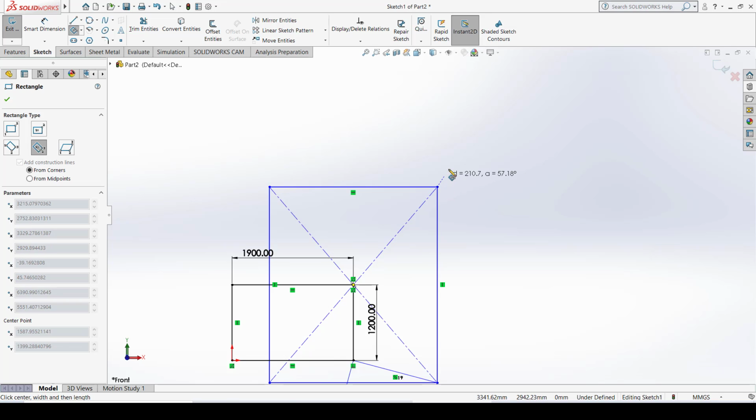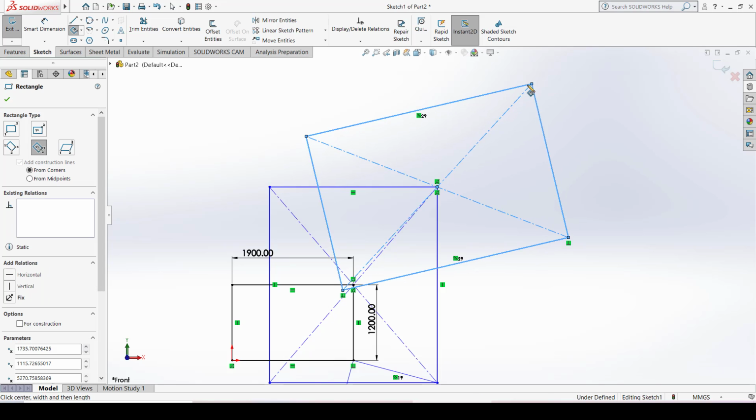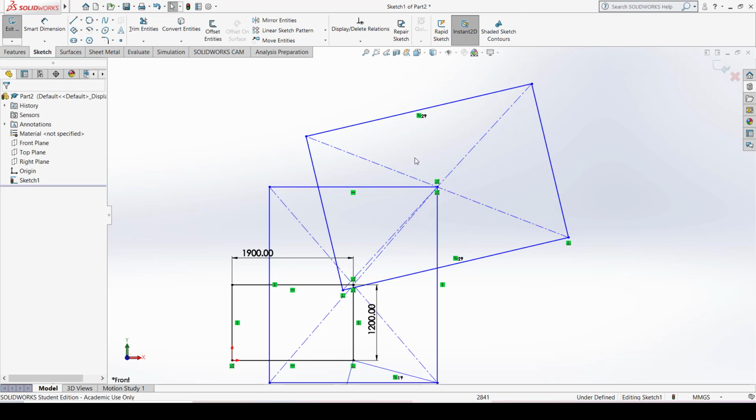Okay, so let us say first is the center of the rectangle. Now you can give any direction, anywhere, down, upward, clockwise, anti-clockwise, it's up to you. Let us say I give this here. From this point, this is the midpoint of the expansion. When I drag my mouse, see what happens now. This point is the center of the rectangle, and then I drag my mouse to this point, which becomes the midpoint of the expansion. From here I can drag the mouse upwards or downwards; rightwards or leftwards doesn't appear, but upward and downward appear. When I make it in the up direction, this is the third point, the end of the expansion, or we can say the corner of this rectangle. Fine, so this is how you can create the fourth type of rectangle.